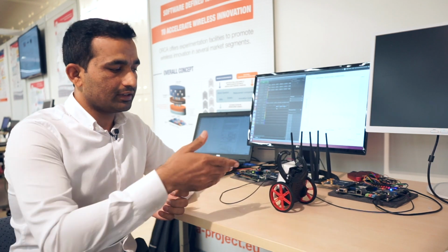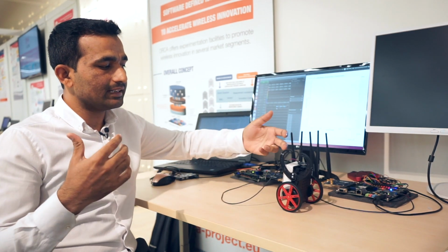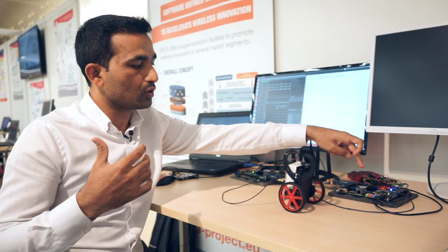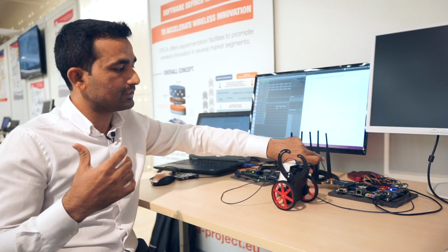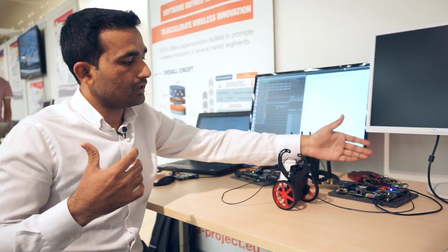You can see that the robot is almost balanced here. The robot is working on a TDMA scheme in the MAC layer. In TDMA we have beacon slots, TX slots, RX slots, and non-operational slots, so we have a customized super frame here. The basic flow is like this: we send sensory data to this node, that node sends the data over the air to the other node, and it sends data back to node 1.